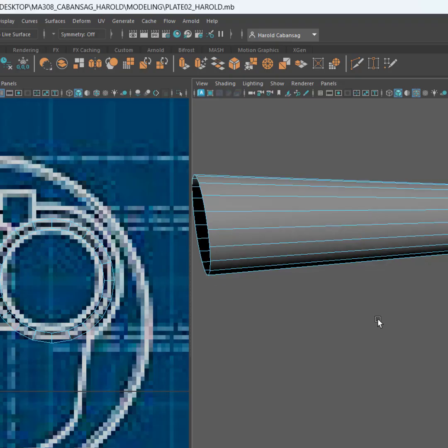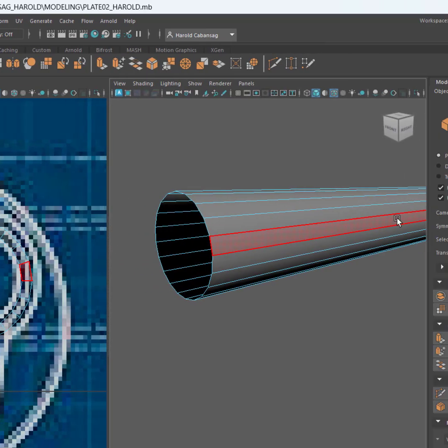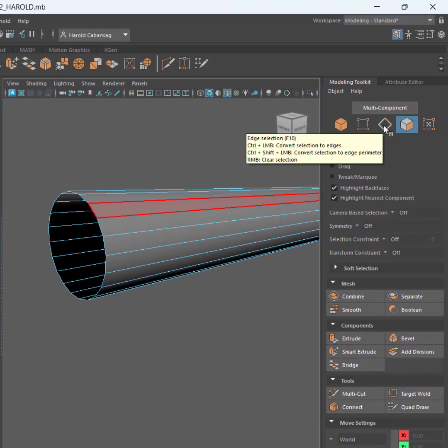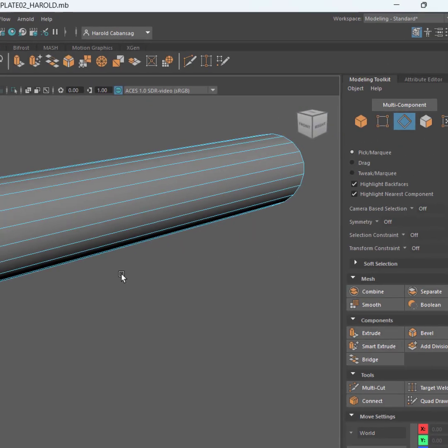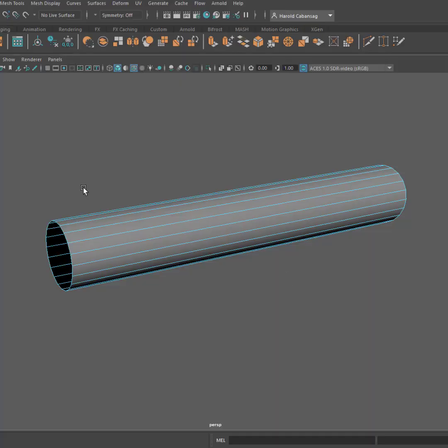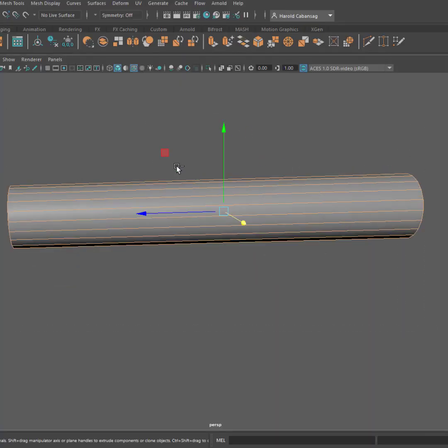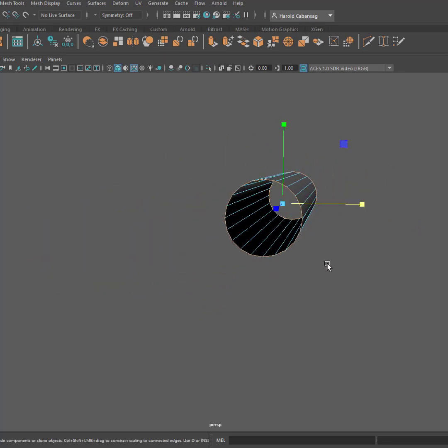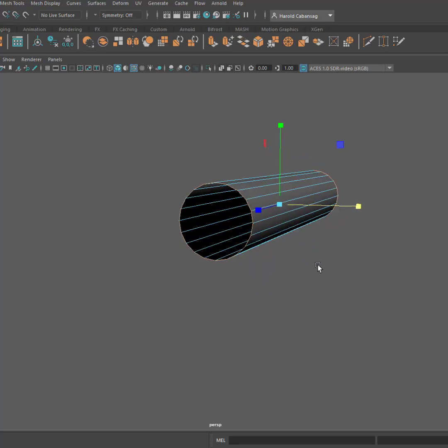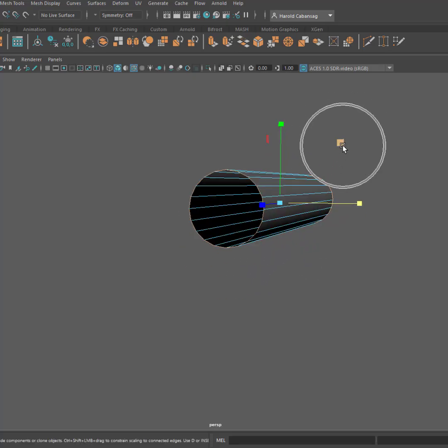So to be able to add thickness to that, I will just hold the polygons, the edge selection, maximize this view again, the perspective, drag and select all, and then deselect the ones that I don't need, and then I can press R to scale, and then I will scale along this, right?